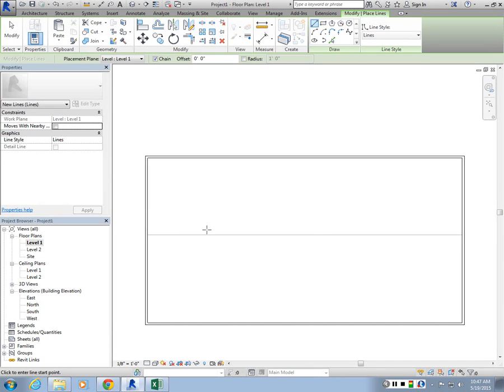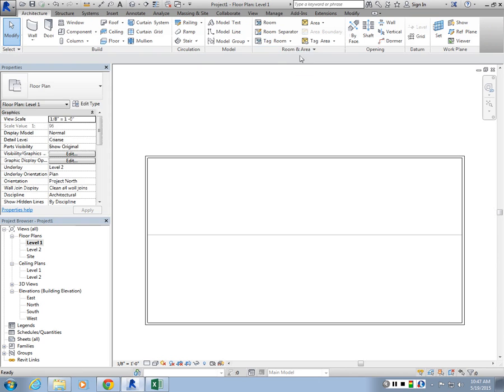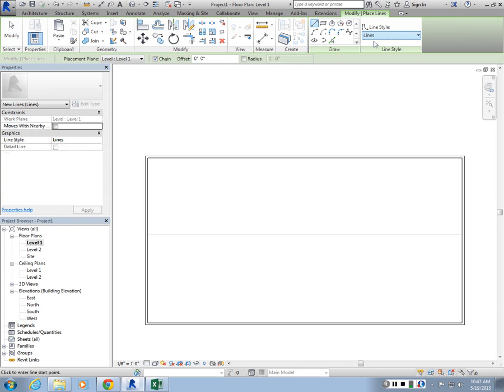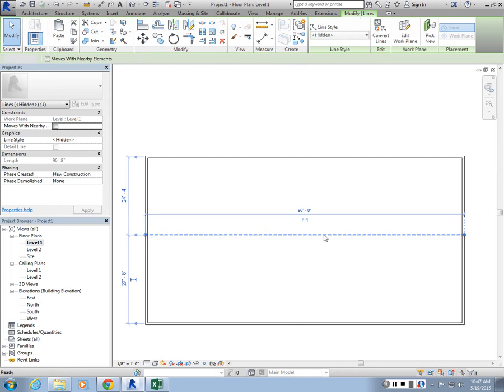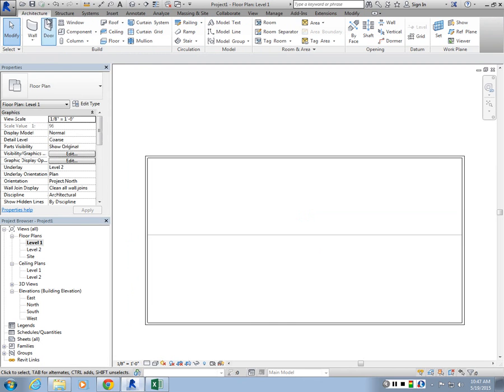And if you want to also draw the overhanging elements above each floor, you may want to draw it using dashed lines. So you can go to, let me see, the model line, hidden, pick lines, and you can do that. Yeah. So you can basically draw it as a model line. So you can go to architecture.